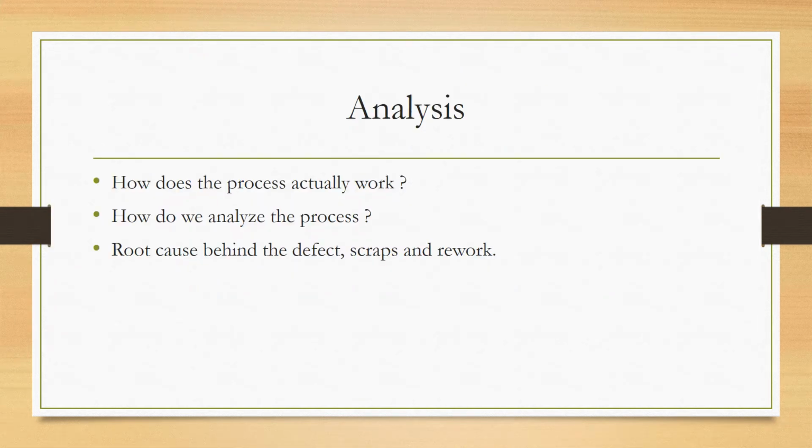Analysis. During the conduct of the analysis phase, in order to estimate the source of defects, like improper surface finish, improper filling, that is porosity, holes and threads, burrs and chips, etc., several observations were made in the workplace where this process is carried out. Furthermore, we discussed this process with the engineering and quality departments, and we interviewed some production associates in order to understand the root cause of defects.